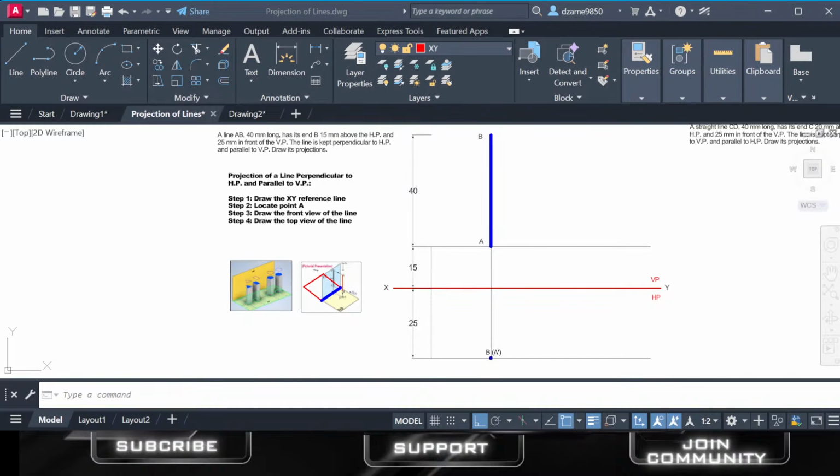Now we're going to locate it. B is 15 millimeters above the HP, so it's front view. Remember, I said again, its front view, which would be B prime, would be 15 millimeters above the XY.